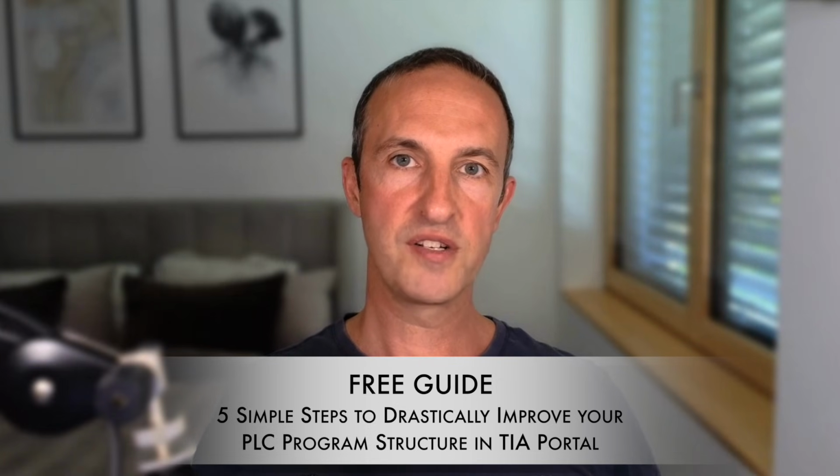And what's also very important, it's independent of the language that you use, because there's so much talk about which language is the best. I don't get mixed up in those conversations because I don't think it's the most important. Some people like ladder logic, some people like structured text, some people like function block diagrams. Personally, I don't think that's the most important for a PLC programmer. I think structuring your logic, knowing how to organize your logic, how to make modules is much more important. And that's what makes the difference between a very good programmer and just a standard PLC programmer.